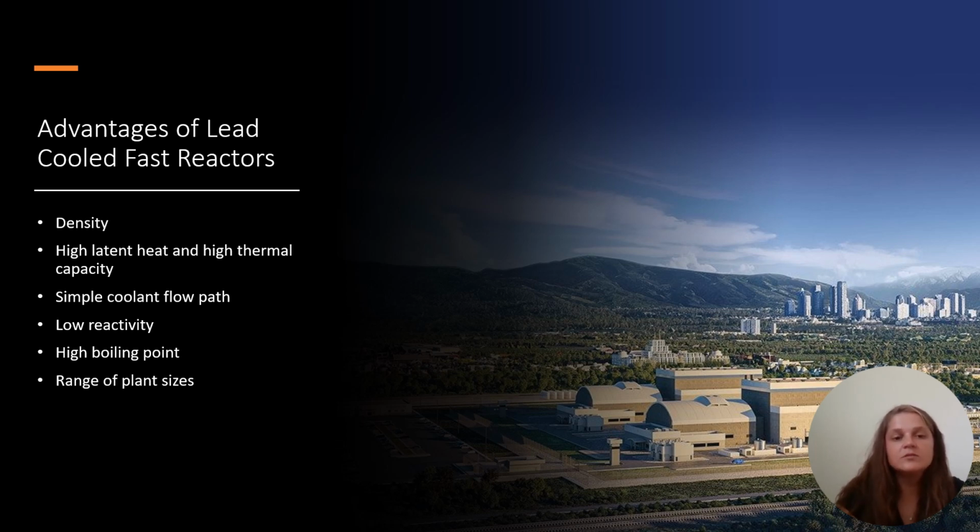Lead does not react with coolants in either water or air, so in the event of a leakage, there will not be rapid chemical reactions like there would be with the sodium-cooled. Lead also has a high boiling point that allows the reactor operation at or near atmospheric pressure and eliminates the risk of core voiding due to coolant boiling. This also leads to higher safety margins and the ability to operate at higher temperatures.